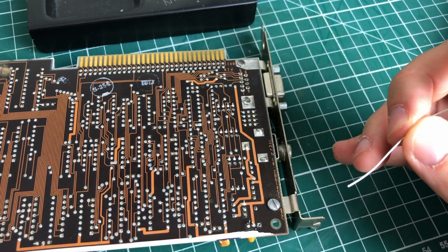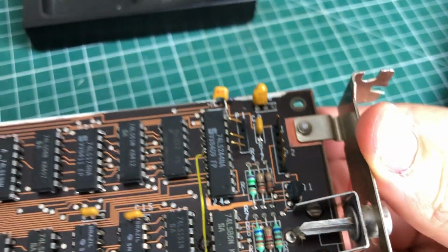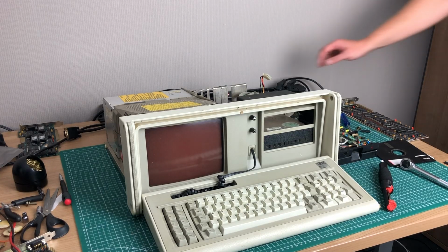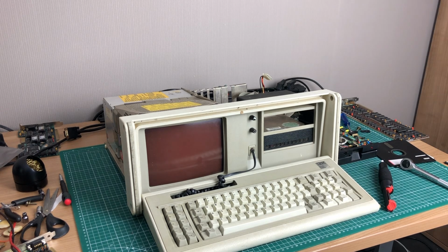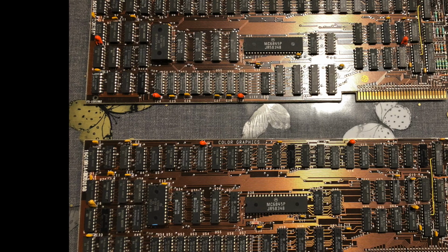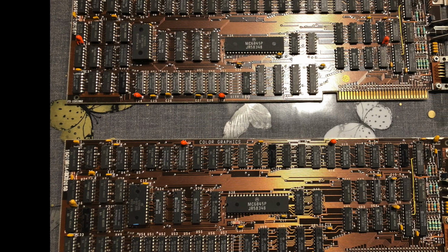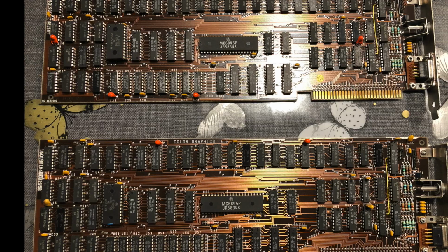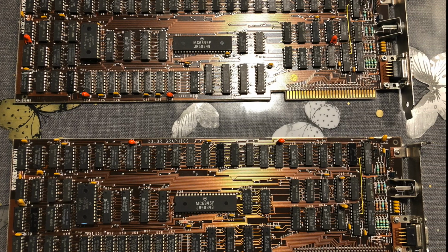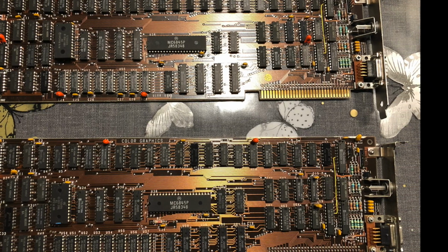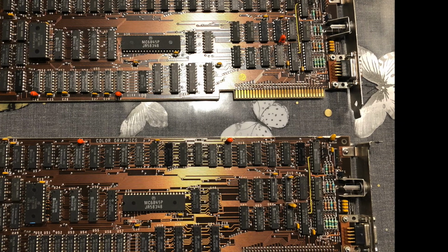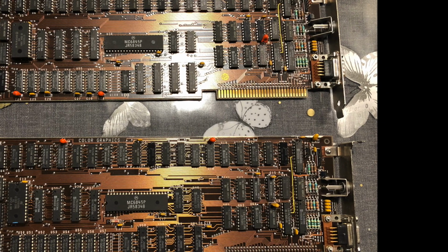When I started the PC with this CGA card, I got the long beep followed by the two short beeps, indicating there was still an issue with the video card. Now I do have a spare CGA card, so I had enough hardware here to do comparisons, check values. Everything seemed to check out, even on the faulty CGA card. I didn't find any shorts.